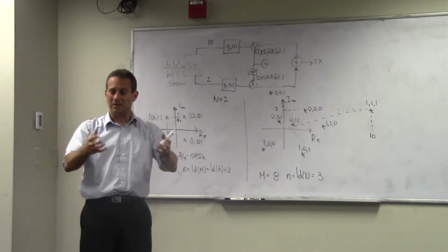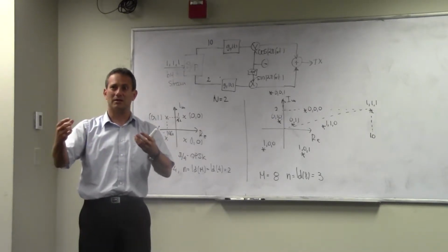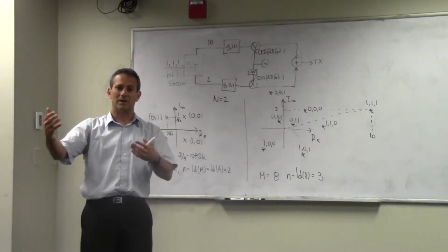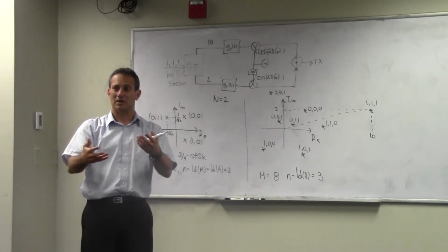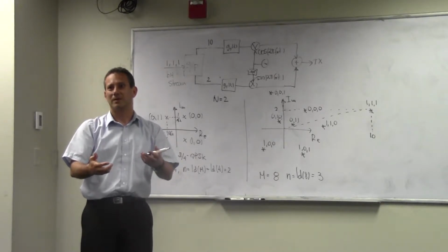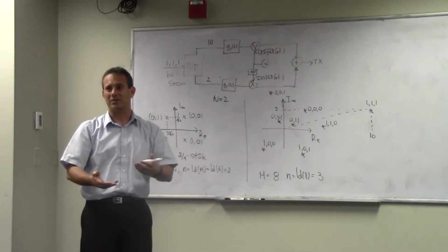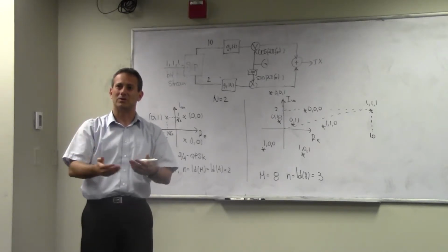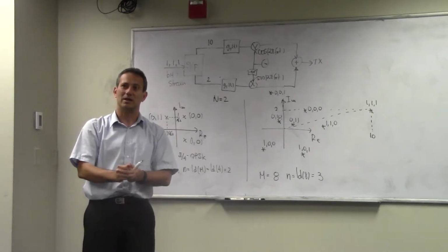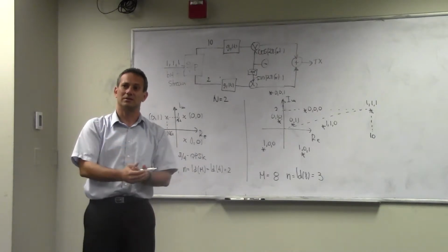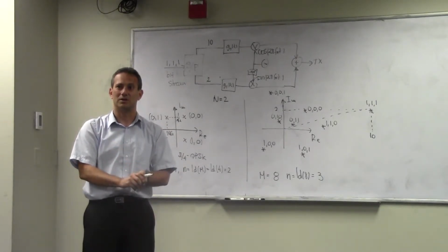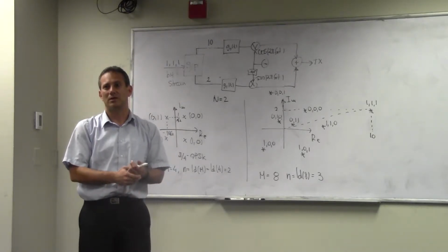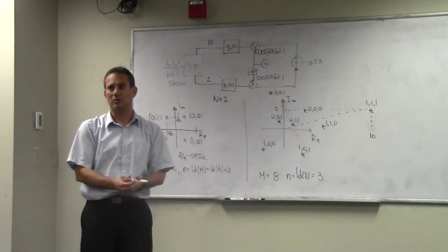So the most natural way of dealing with it is to use exponentials. Practically, in our circuit design, if you have sines and cosines, we devise a math that allows us to treat them as if they were DC. It's just that they're complex kinds of DCs. Remember, all of our KVLs, KCLs, and everything works with sines and cosines in steady state as if they were DC voltages and currents. So our life is really easy with sines and cosines. That's practically why we do it.